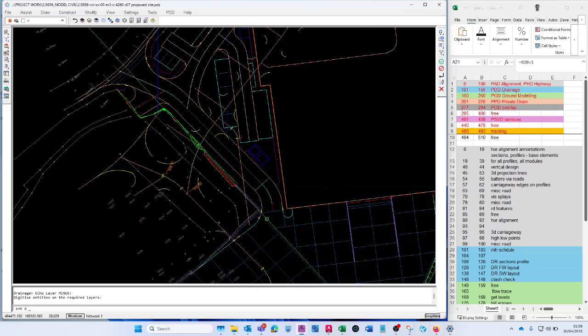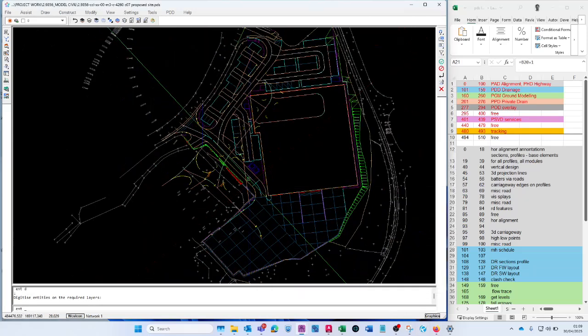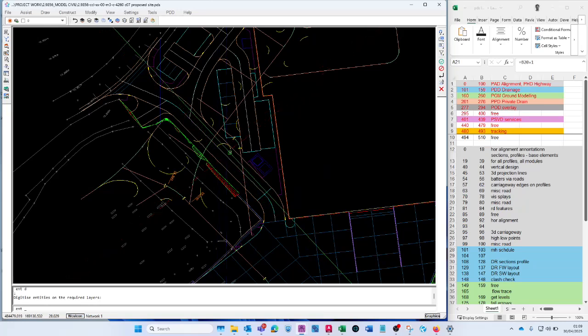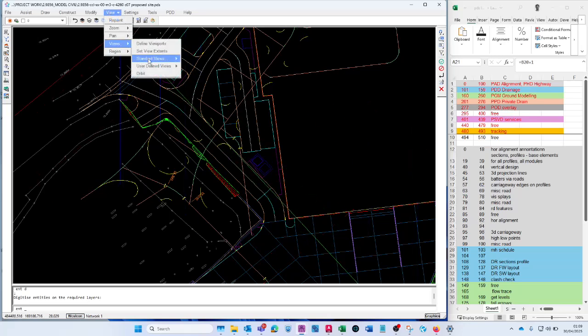If I turn that one off, and then when I create your carriageway, it is basically drawing a center line that hangs off of that massive string, and you have your center line and your curb edges. So if you got your road, for some reason again you can't see it, your carriageway 90 to 92, they're probably turned off. If we go back to the top,